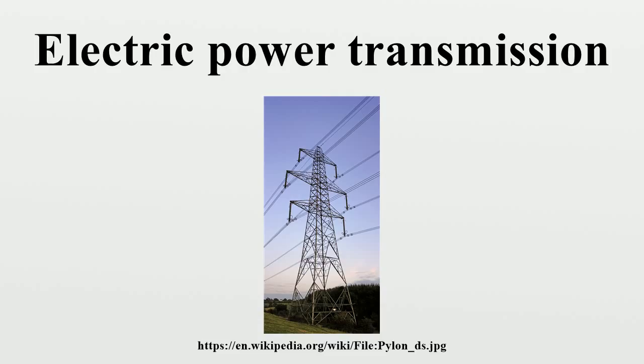A few months later it was followed by the first British AC system, which was put into service at the Grosvenor Gallery, London. It also featured Siemens alternators and 2.4 kV/100 V step-down transformers, one per user, with shunt-connected primaries.